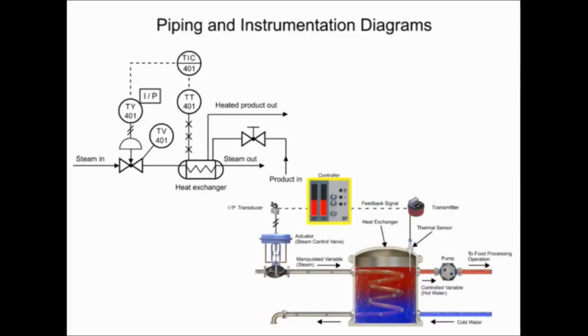The controller indicator in the instrument with the transmitter sends an electrical signal and is shown in the functional identifier at the second and third letter. I and C balloons with the solid dividing lines indicate the instrument is board mounted. An electronic signal from the controller is indicated by the dashed line.